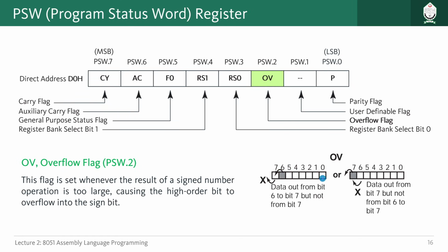So the rest of the 7 bits are used for arithmetic operation. If after any kind of arithmetic operation, any overflow happens from the 7th bit to this 8th bit reserved for sign, then we say overflow has happened and the overflow flag will be set. So that is the idea. But arithmetically, there are some very complex details to understand. Whenever we talk about that in the specific chapter, we will go into the detail of how that happens. But for now, we can skip that, no problem.